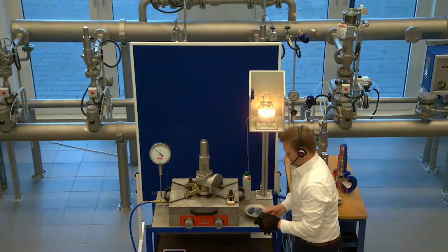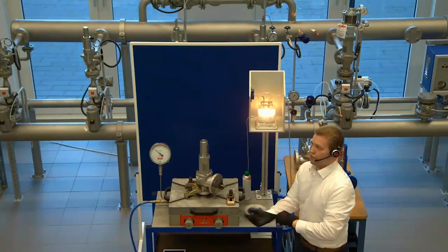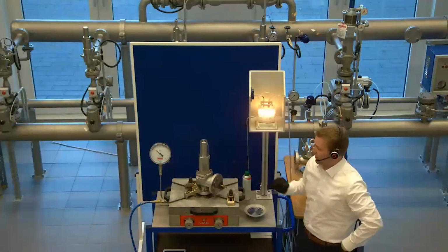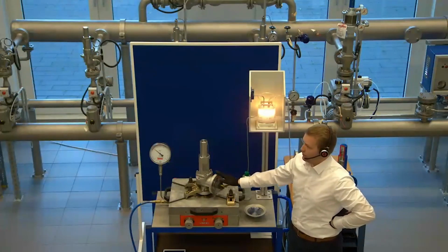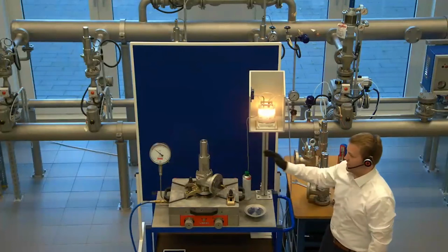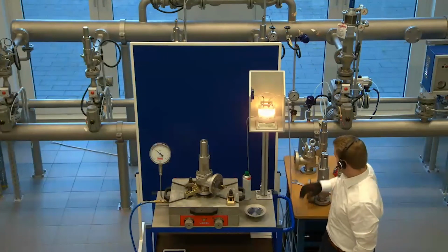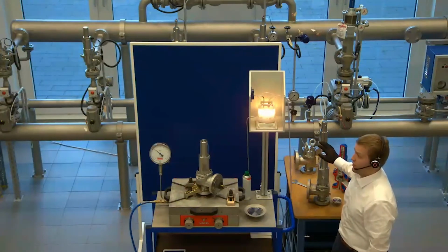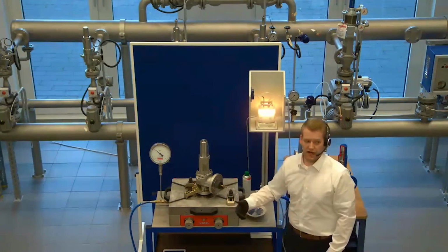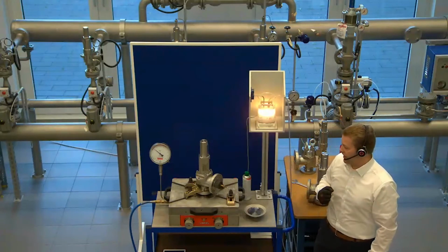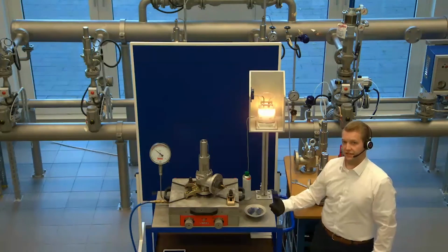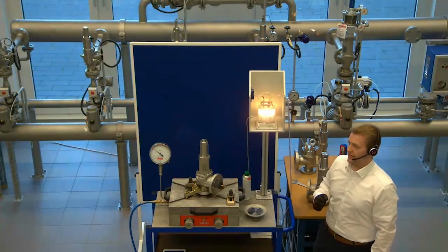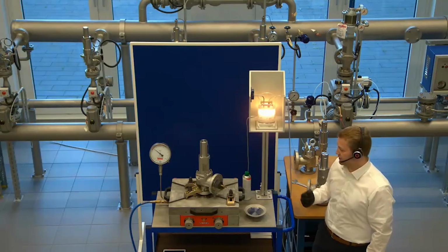So this was our first two live tests here. You see the bubble counting methods for API valve with a metal-to-metal sealing. In this case, we have 0 bubbles in 10 seconds. We have to look into the API 527, and there it states the bubbles per minute. And LESER nano tightness, I explain in some seconds what this means in detail.